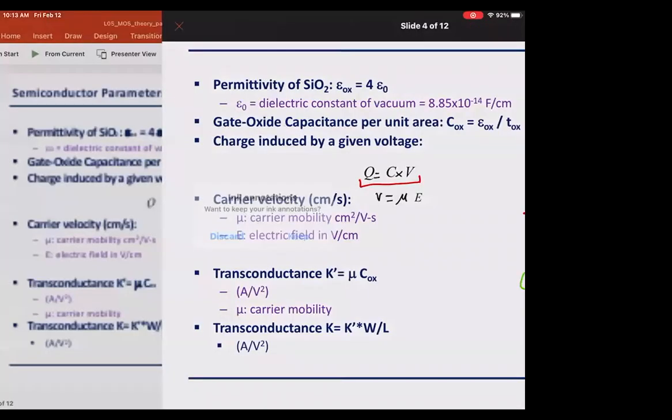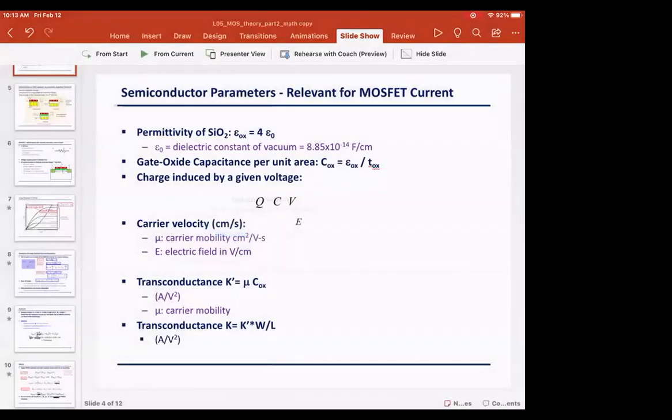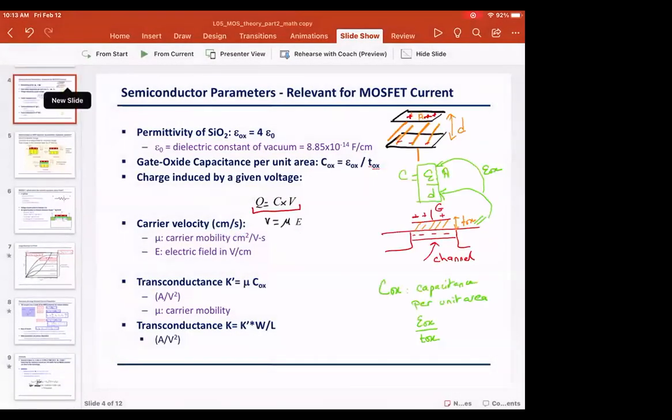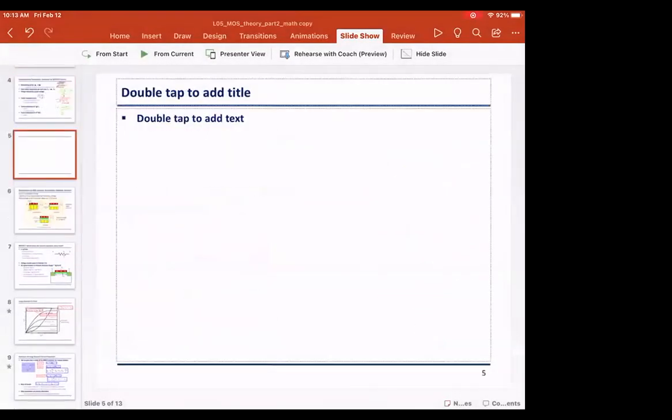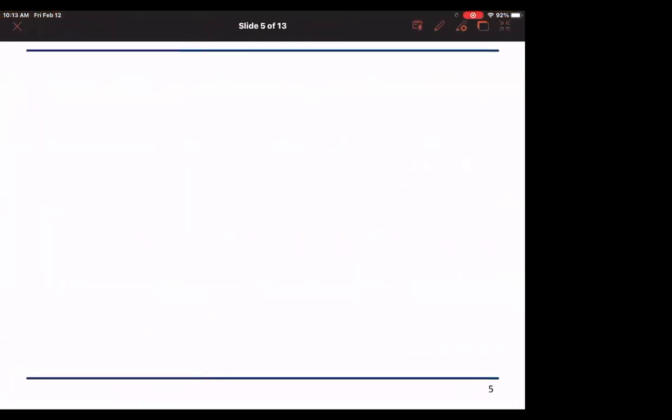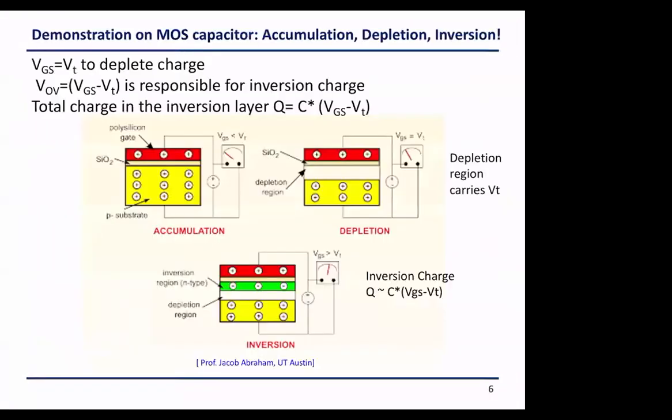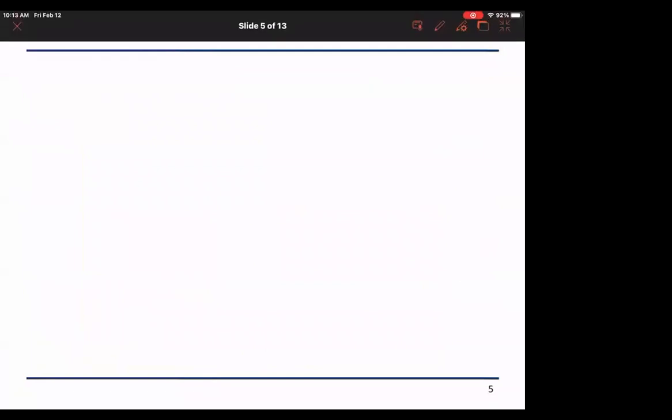Professor, this capacitance, do you consider it a parasitic effect? Is it not desirable, or what do you consider? Is it wrong to think of it as parasitic? Well, it is parasitic for delay, but at the same time, it is the reason why we have charge accumulation in the channel, right? And the gate controls the channel via this field across the capacitance, right?